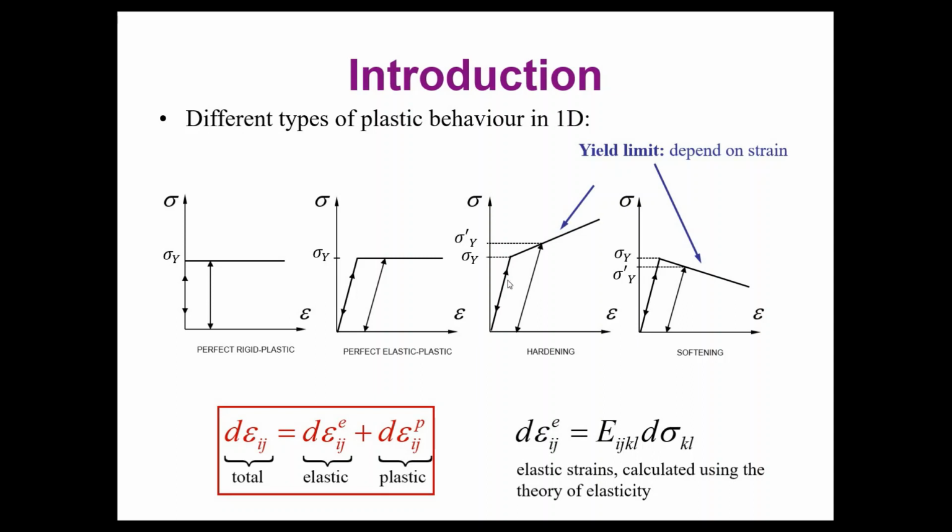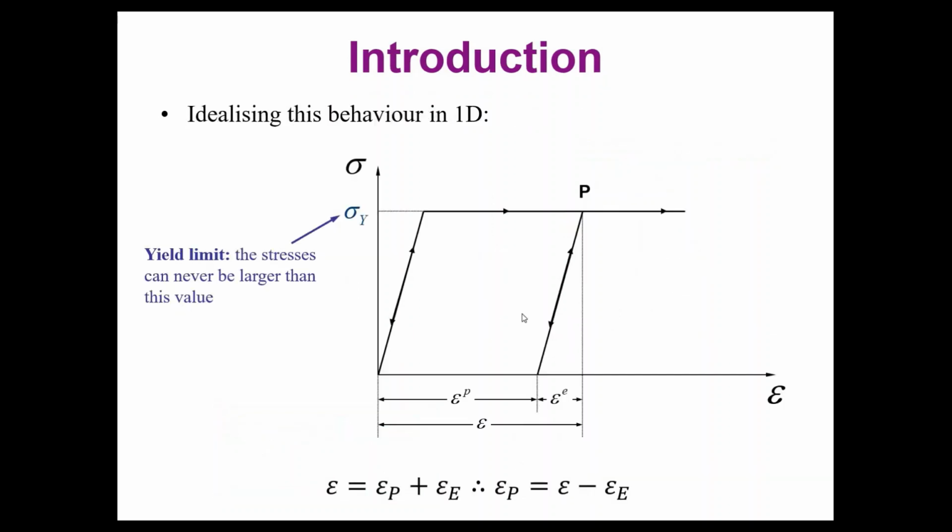So in this case, for example, we have a linear elastic regime at the beginning, and after we have a sudden change, we have a second line that represents the plastic regime, and when we unload and reload, we are going to be able to capture the improvement or the increment in the yield strength of this material. So we are now able to reproduce more or less what happened in reality.